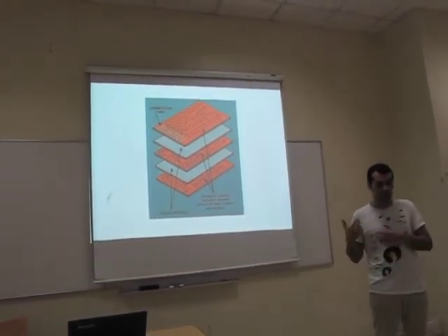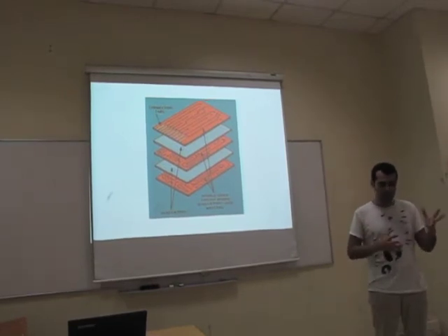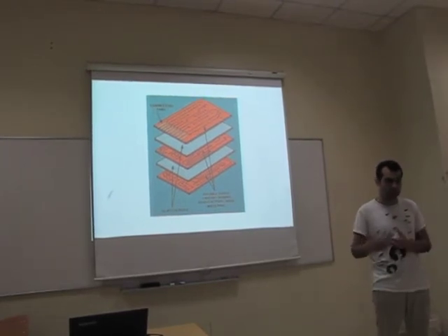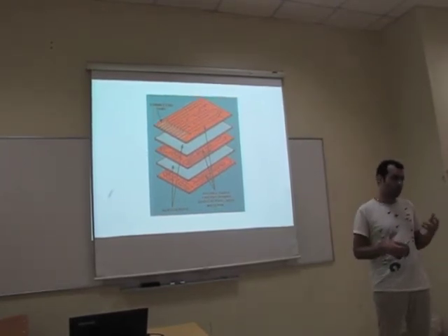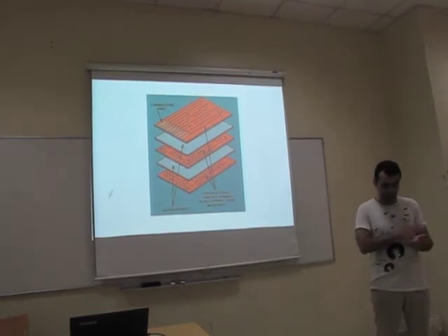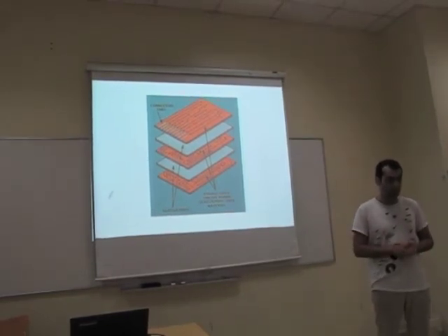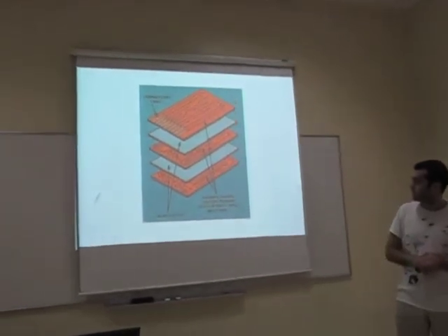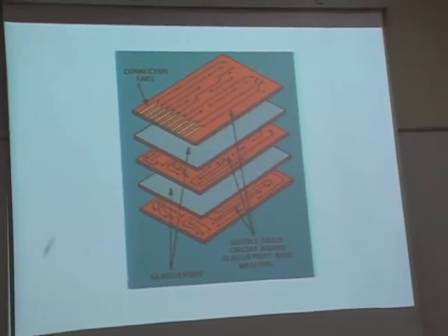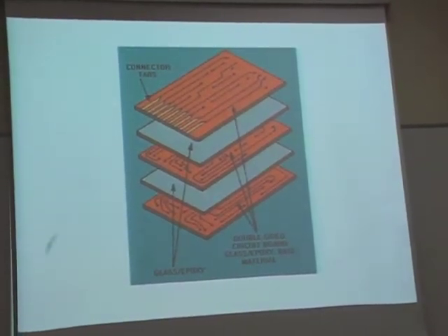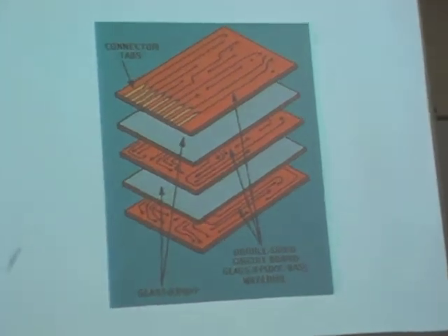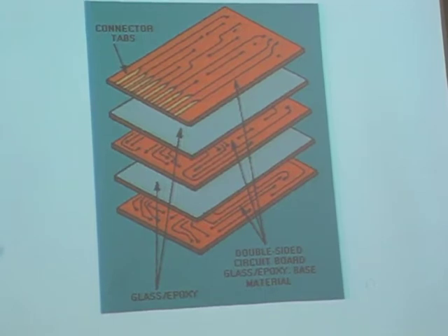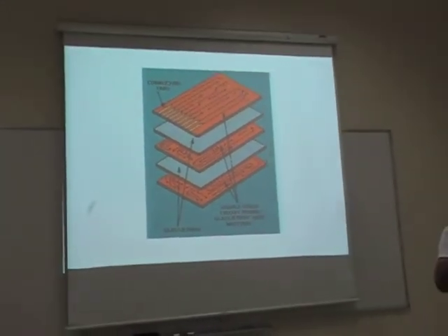The good thing is, when you connect the wires together, it's sometimes hard, but sometimes you have more flexibility. You can connect everywhere to everywhere. But on a PCB, we are working on a 2D plate. If you want more, you need to go to more than 1 layer. So this is one of the schemes you can use. There is more than 1 layer on each other, one on the top, one on the bottom, and there can be many of them in the middle. The thing we can build in this university is only double layered. One on the top, one on the bottom.